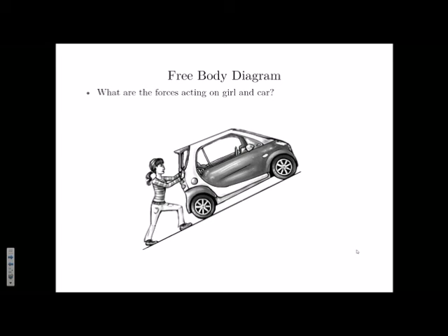Now, it is not just a picture. Let me remind you, a free body diagram is not just a picture that you draw. It is something that you will use to do all the analysis after that. So if your free body diagram is wrong, all the analysis is going to be wrong. And if your free body diagram is correct, it's just a mechanical process to get to the final answer.